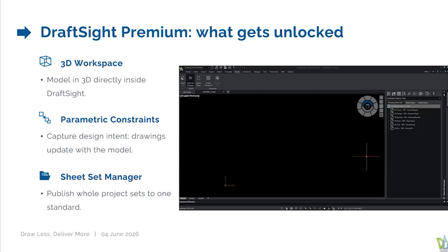So let's say you have a project with 1,000 drawings in one folder, and you're asked to find, maybe, a bracket or a valve, for example. Without it, you're going through a folder with 1,000 parts. With the sheet set manager, you can search the drawing and view it. And also remember, whenever you're designing, and this is just a rule of thumb I tell most people, always name your components so that they're easy to find.